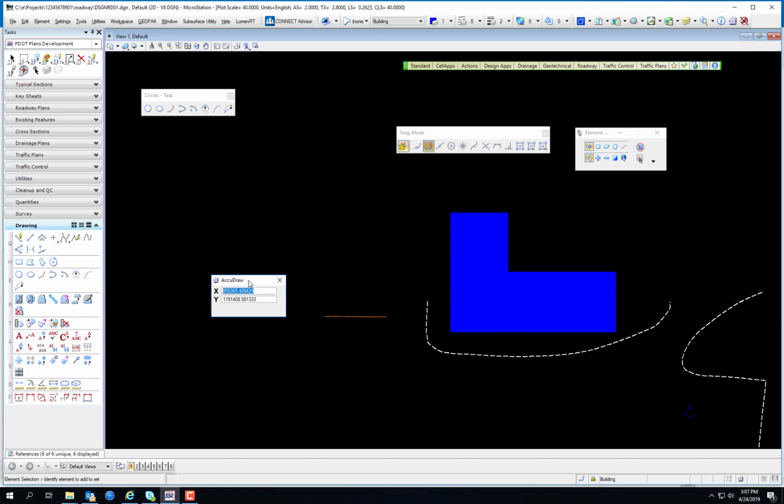And as the book says, the most recognizable AccuDraw feature is its compass, visible only when AccuDraw is active and in control of the MicroStation coordinate input. The compass acts as both a status indicator and a focus for input. Normally, the AccuDraw compass does not appear until the first data point is placed after selecting a tool. AccuDraw's behavior changes slightly with tools that utilize dynamics before the first data point. The Place Text and Place Active Cell tools are examples of such tools.